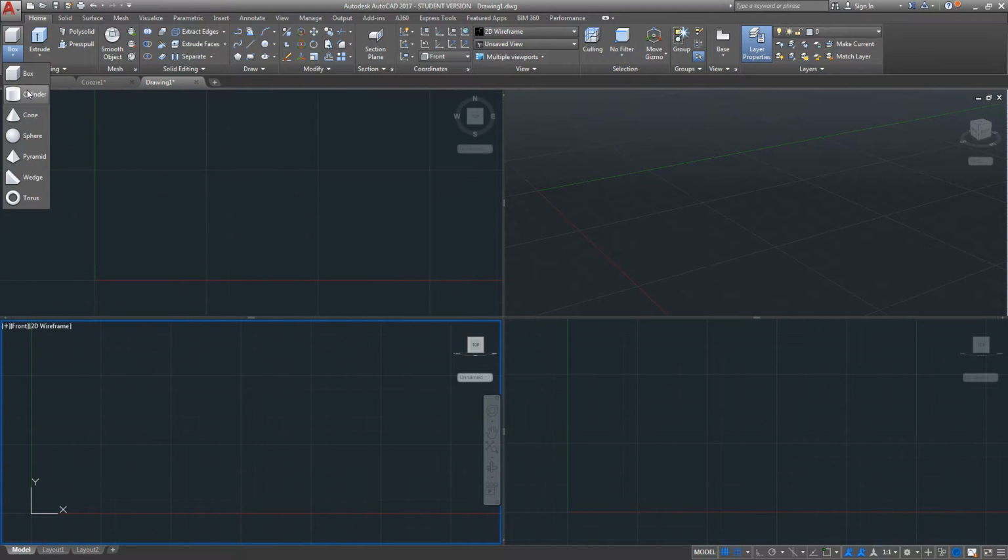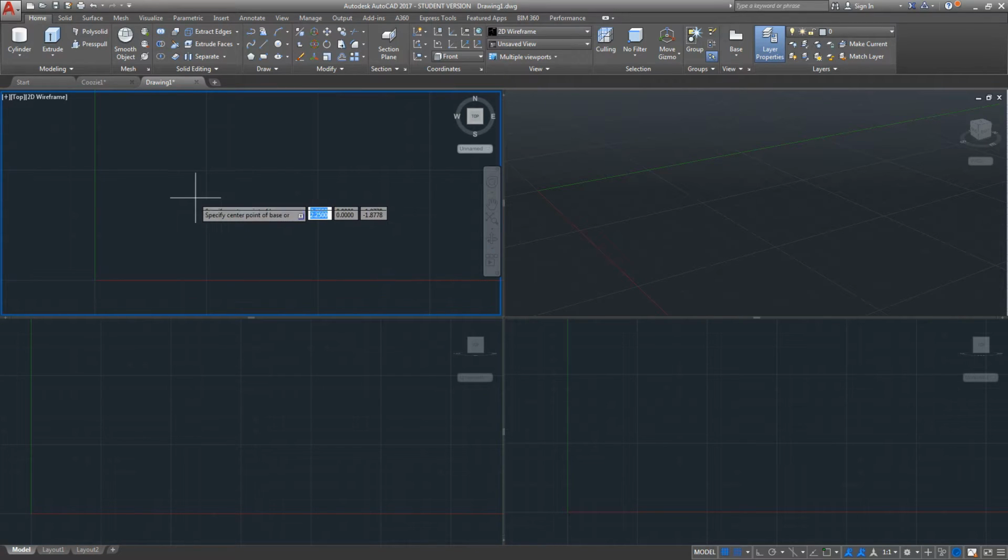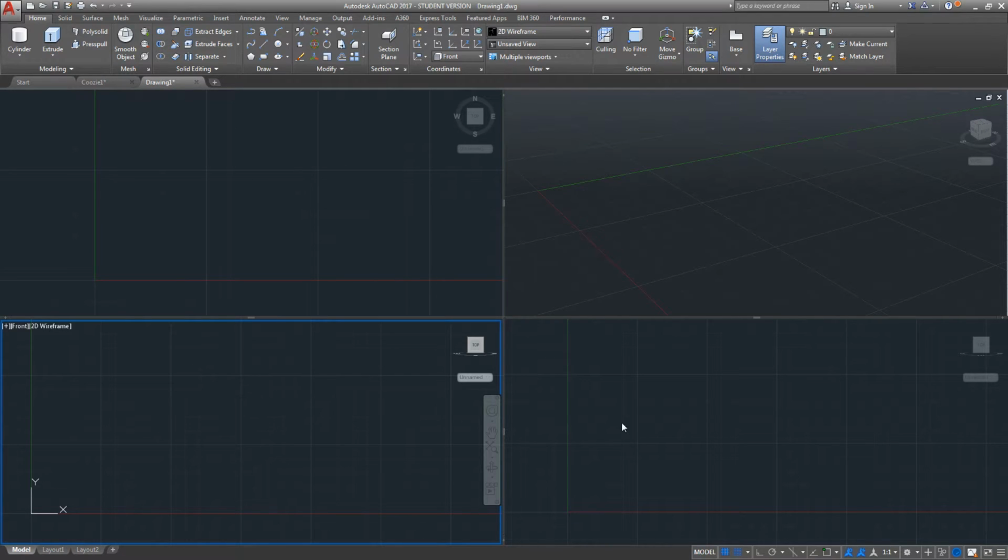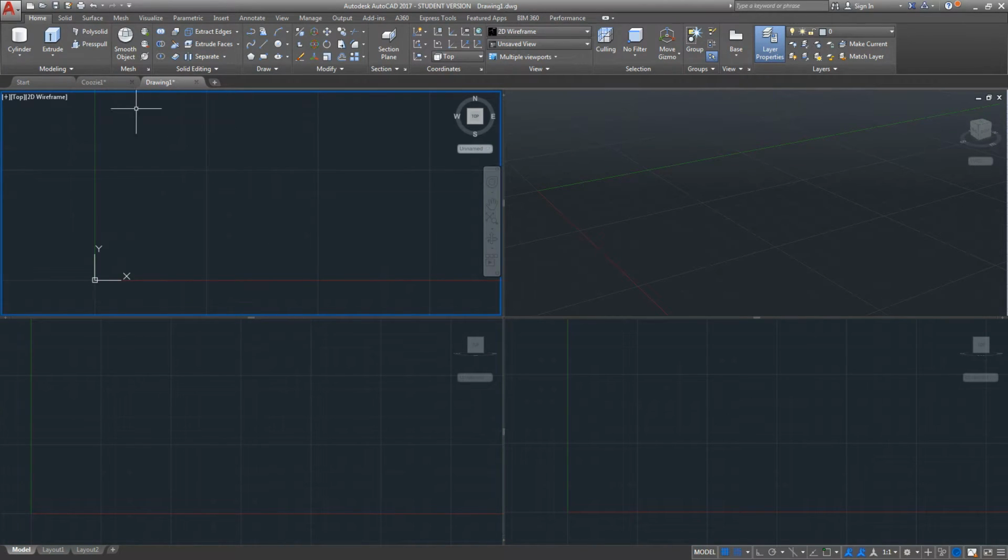First thing we're going to do is start with the cylinder, from the top down. Click the top. This is the top. This is front. This is right to left. Okay? So we're going to start with the top, because it's a cylinder, obviously. It's going to be sitting on a table, right? I don't like to start at the origin, this is the origin point where these two lines meet. Real basic. I don't like to use that, because this UCS, this is the user coordinate system, this little gizmo deal, I don't know what it's called, the UCS point, gets in the way sometimes.